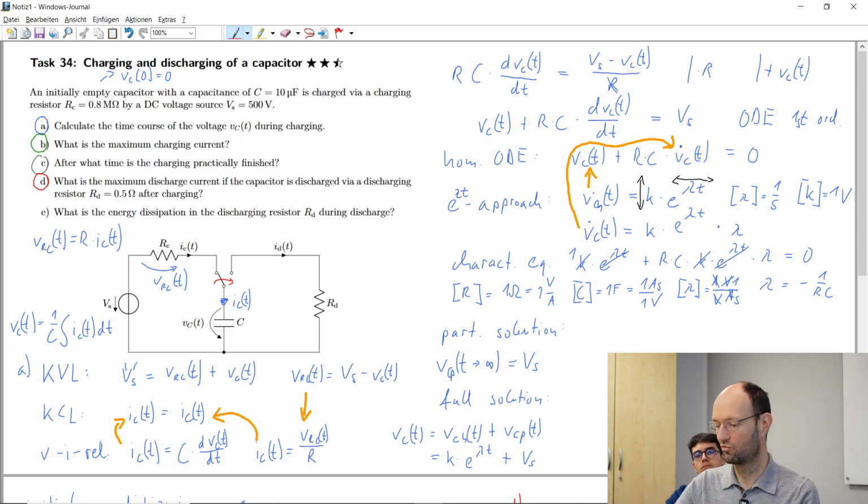If I would get the high current directly from the battery inside the cell phone, which is not super strong, there might be too much voltage drop across the battery. So you take some, I don't know if it's really done this way in one cell phone, let's say, because the batteries are also super strong, but this would be some way. You have a weak battery, you charge a capacitor, and then you discharge it over a short time to get the flash for some camera.